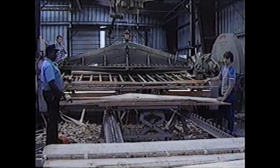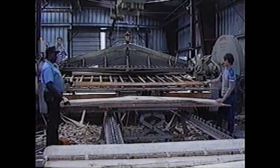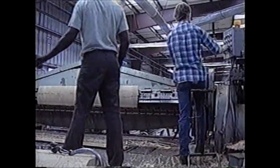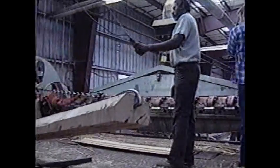Veneer thicknesses range from 1/8 inch down to 1/100th of an inch. 1/85th is a common thickness. The flitch is automatically advanced into the knife until only a thin heartboard remains, which is discarded.